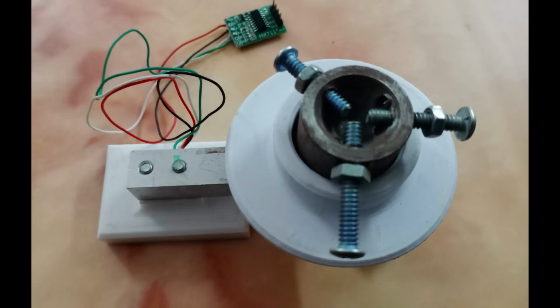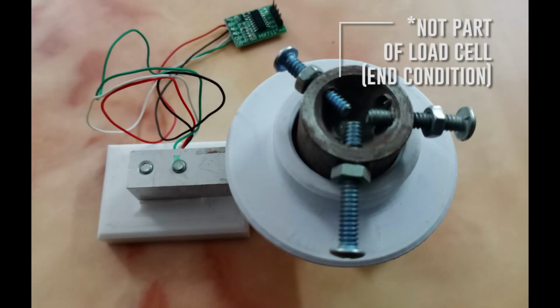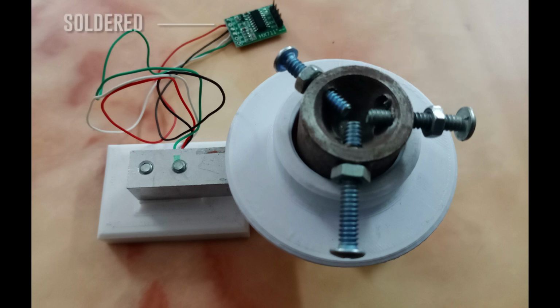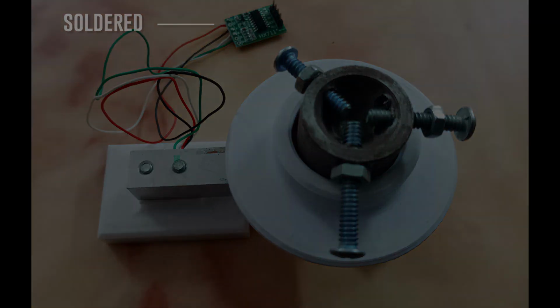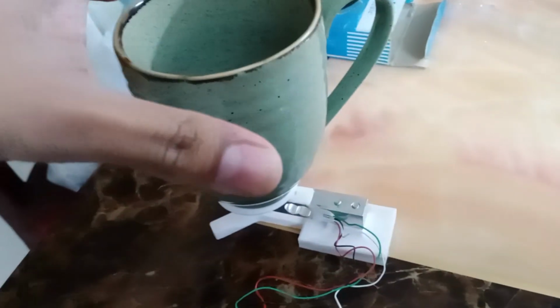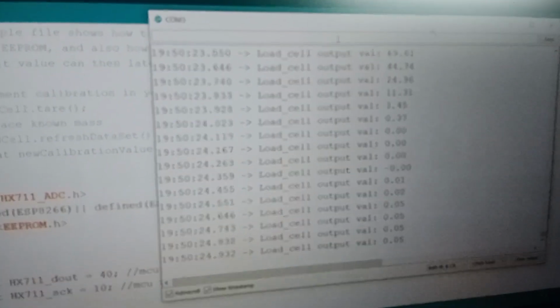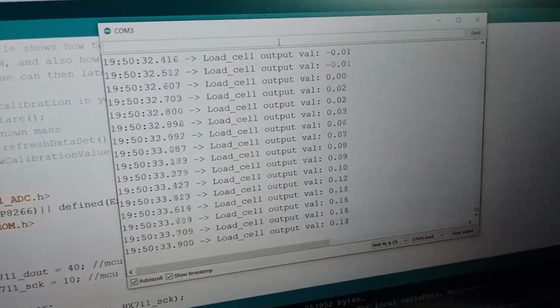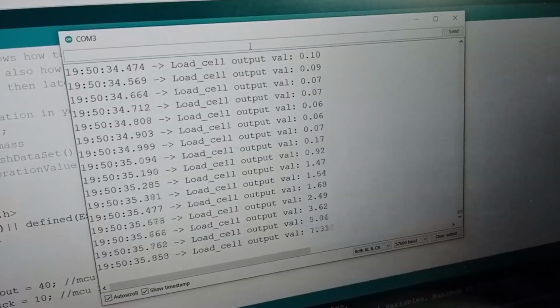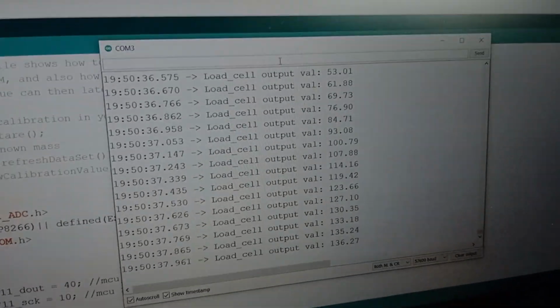So next we bought another load cell from electronics.com, a shop in Farmgate. This time we soldered the load cell wires directly to HX711 without further exposing the wires. This time the load cell worked perfectly. It should be kept in mind that the soldering are not strong connections, and if not handled carefully, the soldering will break apart, which happened in our case. We then needed to resolder again, and luckily for us it still worked.